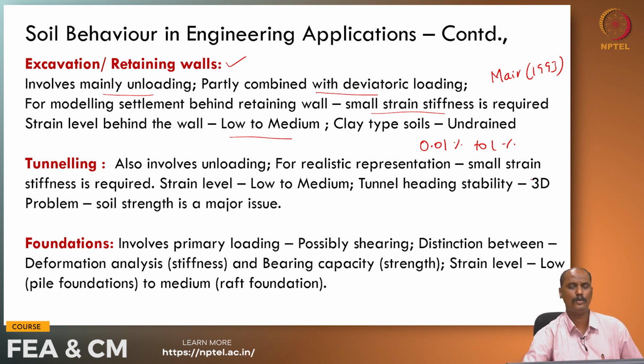The strain level is going to be low to medium, and then the tunnel heading stability is very important to be considered, and usually we go for a 3D type of simulation or a 3D problem, and soil strength is a very major issue when it comes to tunneling applications.